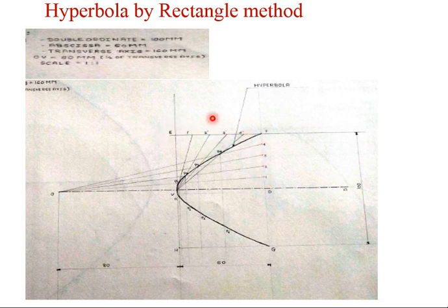So instead of dividing the line into an equal number of parts, you might have used the dividers with the help of a scale, and you have divided it into 5 equal parts. Now join whatever these FD points are to this O, like O4, O3, O2, O1, and this particular V, which is the point on the curve, to V1 dash, V2 dash, V3 dash, V4 dash.